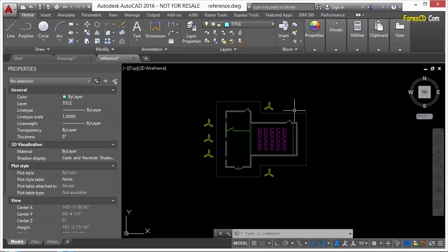So here in this reference file, we see that this reference file is located in model space. When you xref something in, that's typically where you're going to put it, into model space. It's drawn at a 1-to-1 scale, and now you can just act like you have this line work inside this file, even though you don't. You can reference files to paper space, but that's typically only used for images, like a title block or a PDF of a schematic or something like that.